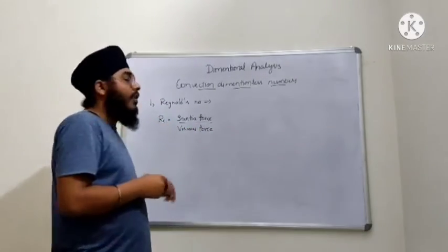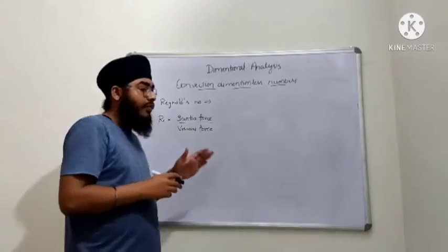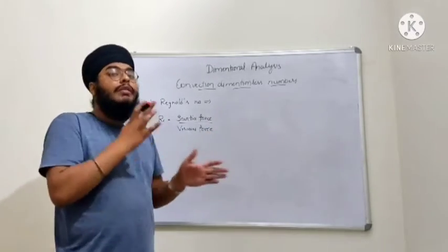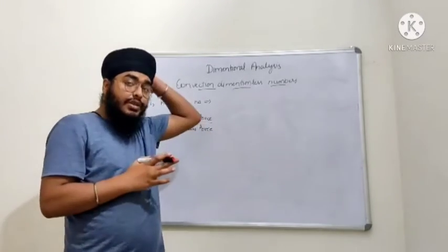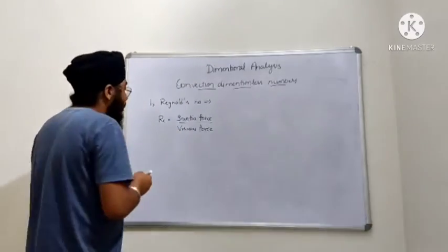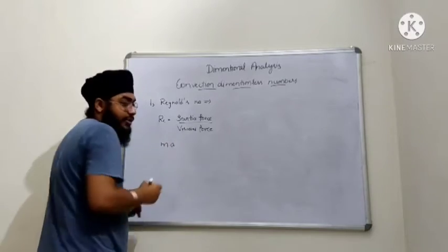Now getting the formula of Reynolds number, we know the inertia force is the force that is moving the fluid, the force acting on the fluid because of which the fluid is having the motion. So let us say inertial force, let us take it as mass into acceleration.